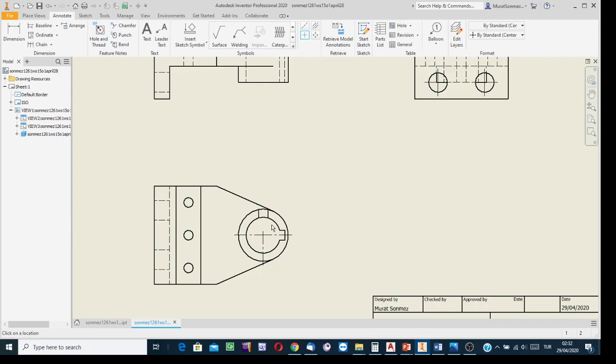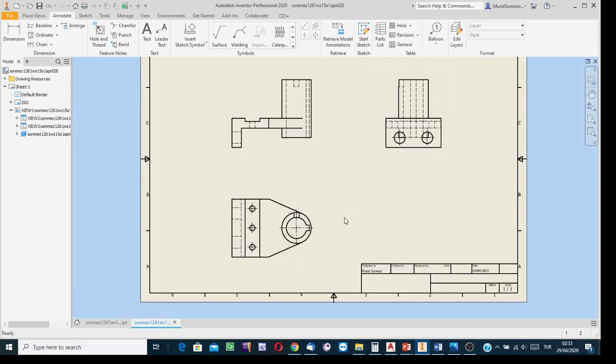But since there is a cutting here, this axis couldn't be created. It is to be extended. I'm going to make this extension after having the axis for the other holes. Indicate, indicate, and press the escape button, and then hold this gripping point, the end of this axis, and then stretch it. Yes, for having the rest of the vertical axis.